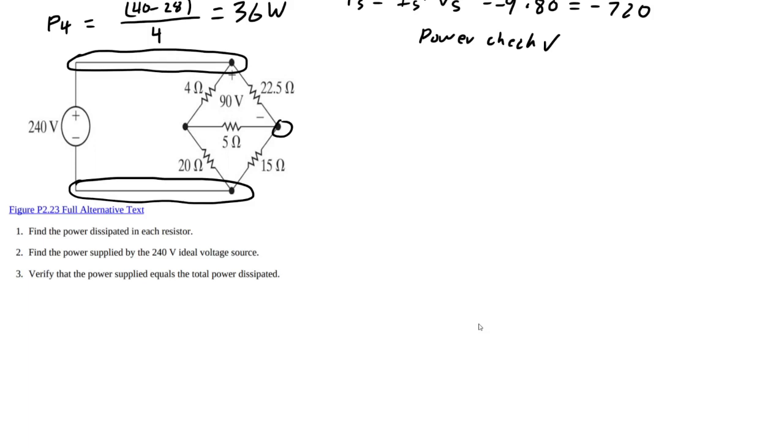So anyway, one thing we can do here actually, we want to set this to be our 0 point. And we know that the problem gives us 90 volts dropped across this resistor, and we're supplied 240 volts. Well, 240 volts minus 90 volts is 150 volts. So this node in particular is at 150 volts.